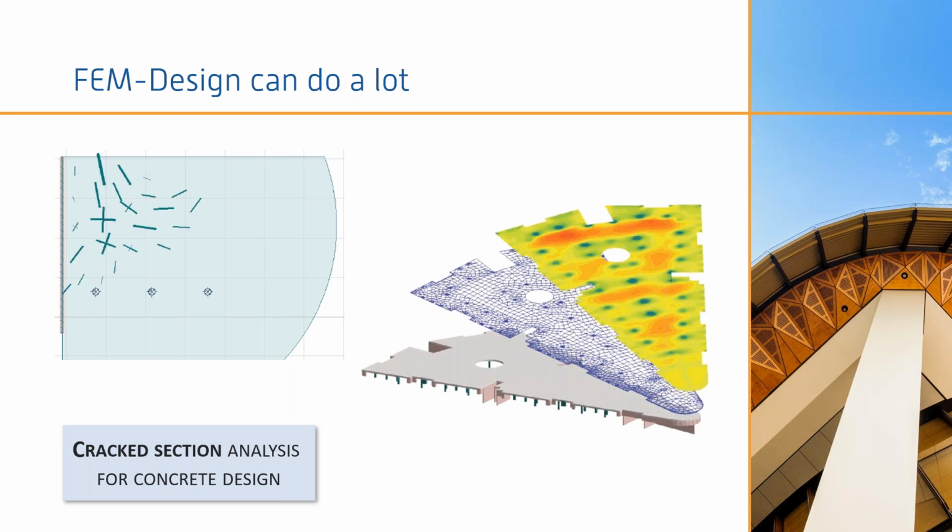So what it actually does is it takes this plate with the reinforcement in it and starts loading it in an iterative process, identifying cracks along the way. Once it identifies the cracks, the program reduces the stiffness in the nodes where the cracks appear and then continues to load it.